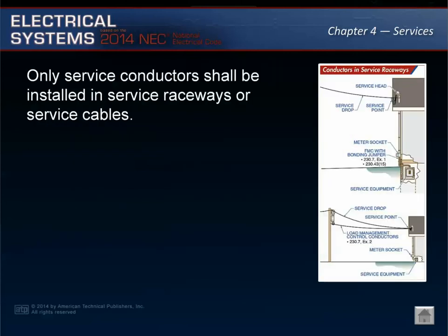Only service conductors shall be installed in service raceways or service cables. Service raceways are not defined in Article 100, but are considered to be any raceway that contains service conductors. Allowing only service conductors to be installed in service raceways ensures that a fault of any type in the service raceway will not affect other conductors.